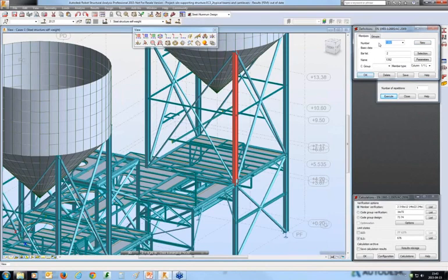To distinguish superbars easily from the rest of the model, you may type a number that is significantly higher than the number of elements in the model. Then in the bar list, you should enter the numbers of the bars that stand for the beam or column. So it is 20 and 21. And you may, for example, name it like left column under a silo.